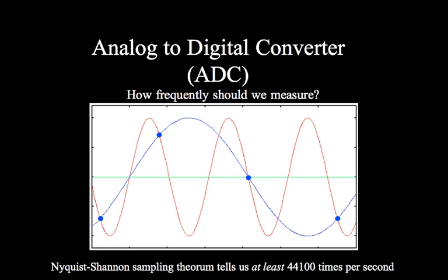Because the question is, can you hear the sampling? Can you hear the sample rate? Because if the computer is taking a picture at a particular cycles per second, if that picture taking is happening within the range of human hearing, you will hear it. It'll sound like a very high pitch because you'll just hear that pattern, right? So let's say that we just do it at 25,000 and we're like, yeah, it should be fine. That's above the range of human hearing.